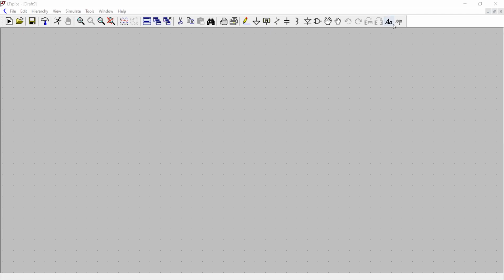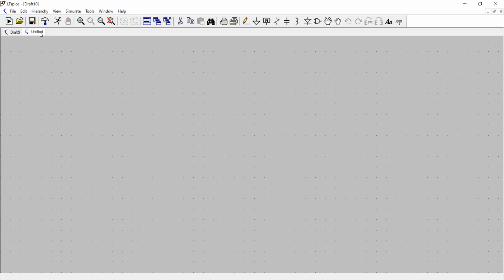Hello. So in this module, we are going to learn how to create positive half-wave rectifiers and negative half-wave rectifiers. So what you do, you have a SPICE circuit simulator, you open it, and then on the schematic, you just click the new schematic. I already have this one. And with that, you then go to the component library.